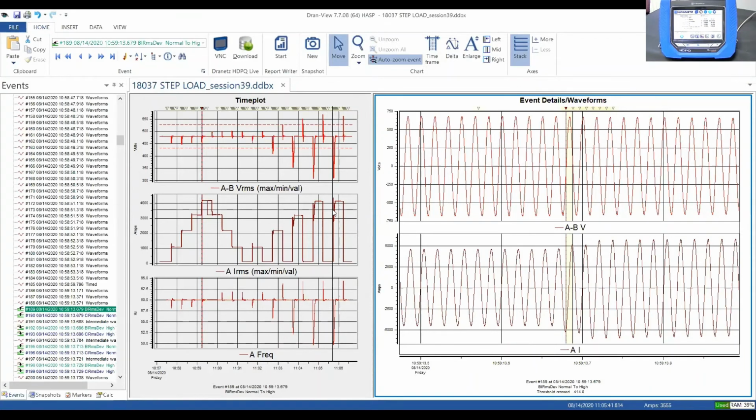Some of the differences that we see are the hold times. We're not the ones to tell you how to properly test or commission the UPSs. I can just share what I've seen personally, and the other guys can chime in. But the hold times vary, sometimes from seconds to minutes. We have a very large standby generator company that holds it for a minute during the process. Others do it smaller, so it probably depends upon the size of the system.